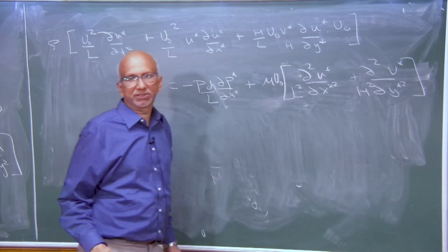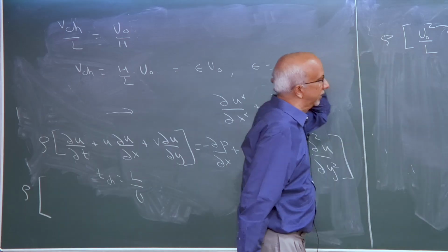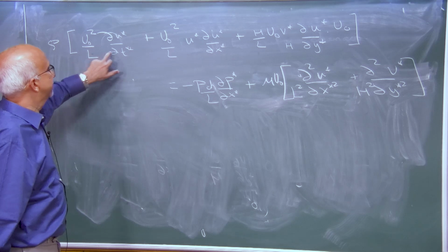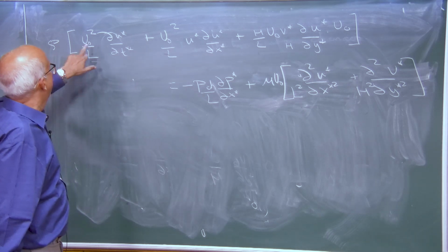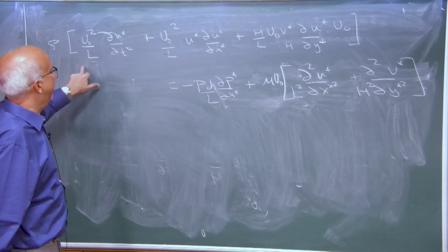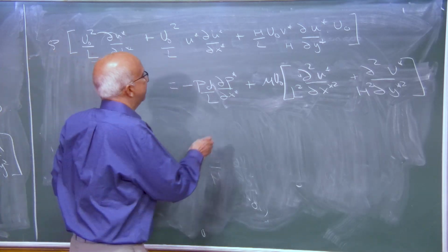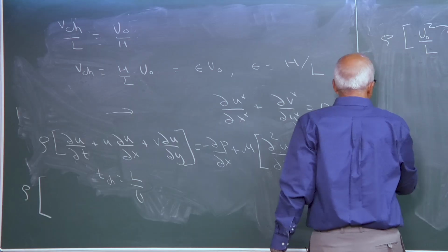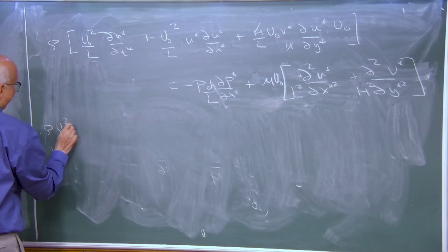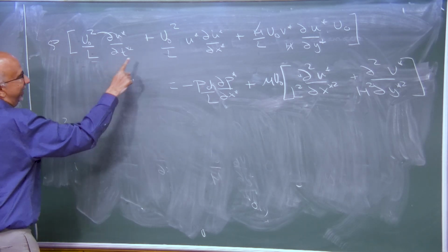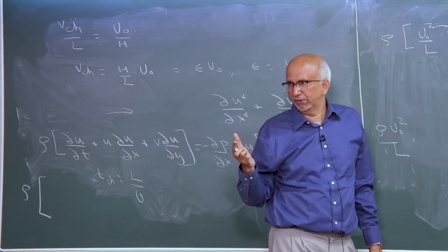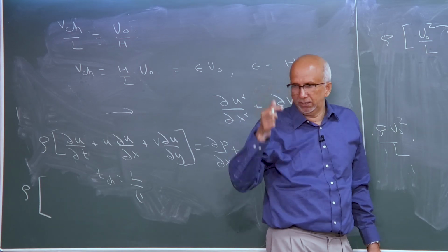By making it dimensionless. So, that is what we have. You see, in all of these terms I have u naught squared by L common because this h cancels off. Okay. So, I can write this as rho u naught squared by L, and instead of writing 3 terms every time, I am going to write it as a substantial derivative capital D, which we did long ago.